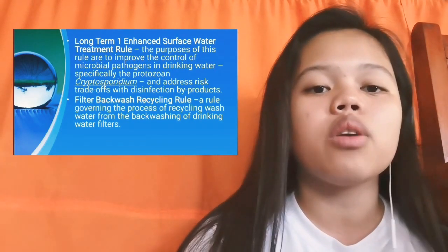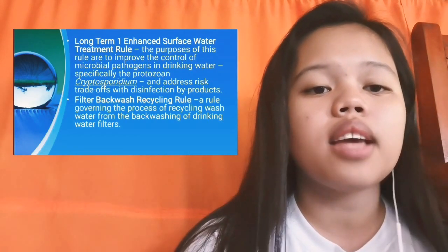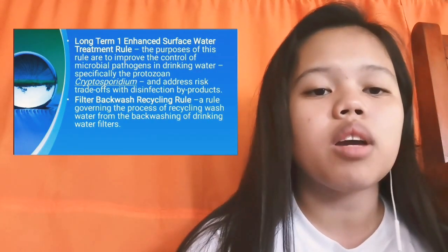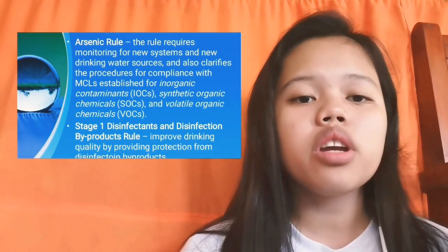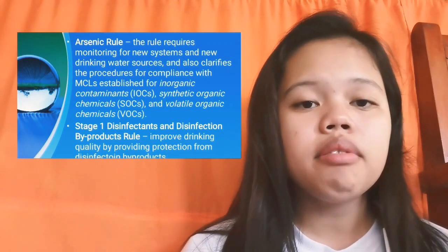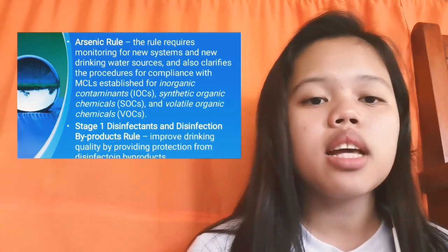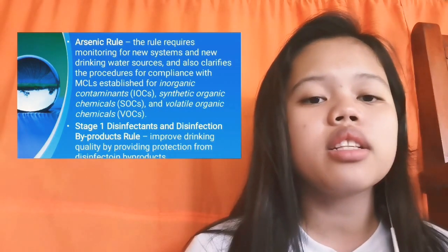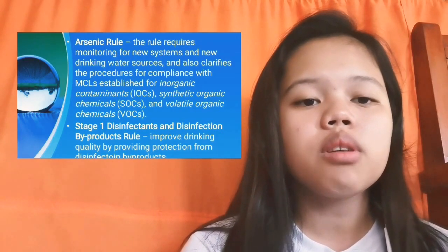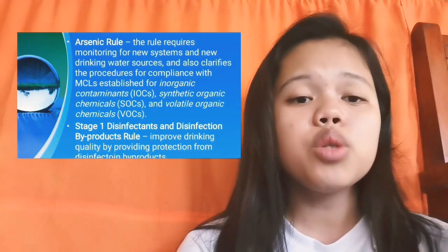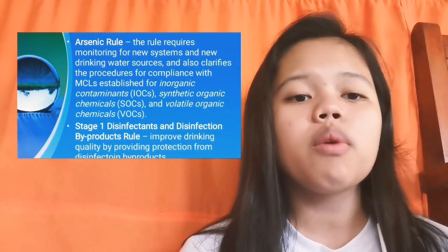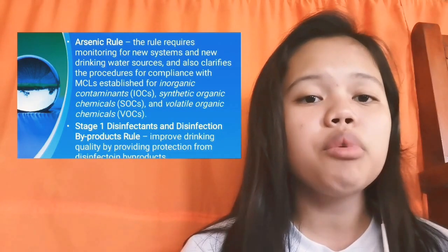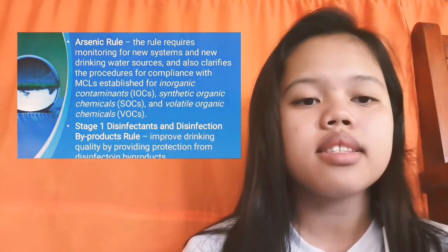Filter Backwash Recycling Rule, a rule governing the process of recycling wash water from the backwashing of drinking water filters. Arsenic Rule. The rule requires monitoring for new systems and new drinking water sources, and also clarifies the procedures for compliance with MCLs established for inorganic contaminants, synthetic organic chemicals, and volatile organic chemicals. Stage 1 Disinfectants and Disinfection Byproducts Rule. Improve drinking water quality by providing protection from disinfection byproducts.